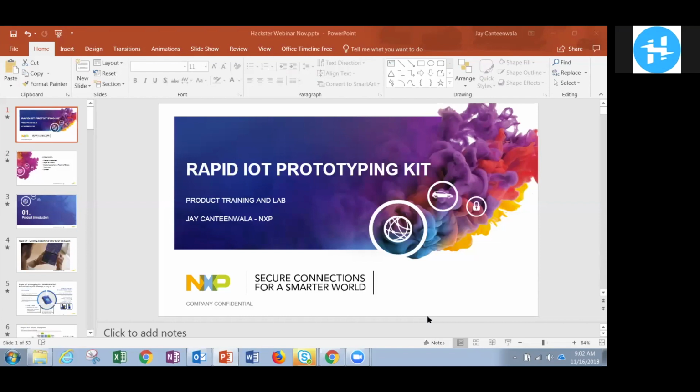When you go to the SDK, which is the C code level, you have 2 targets. One is K64, which is everything related to the application: the screen, the sensors, the actuators. Another folder is related to KW41Z, and here you will find everything related to the Bluetooth or Thread and soon Zigbee stacks.